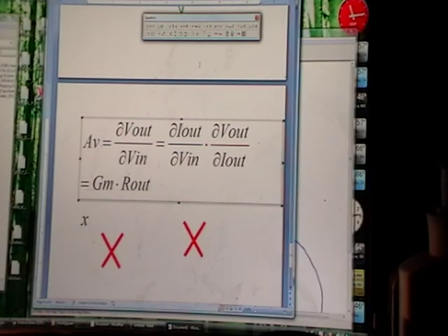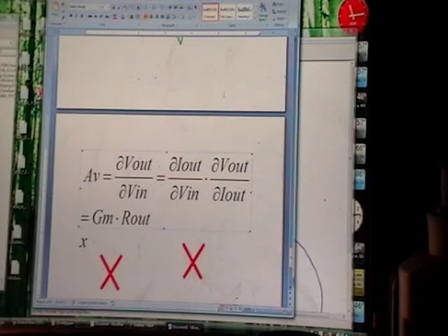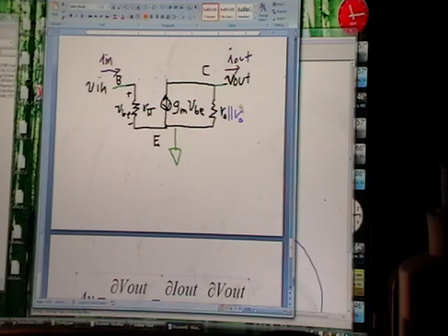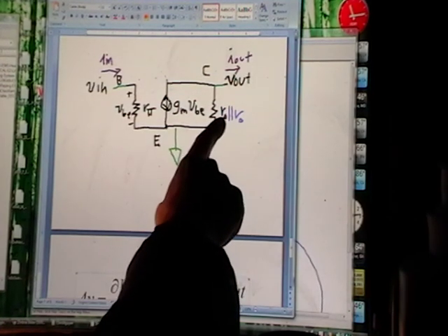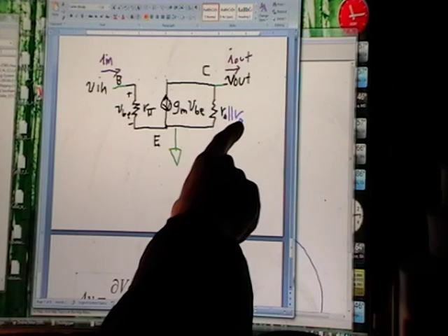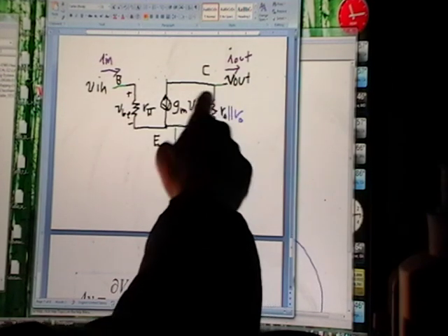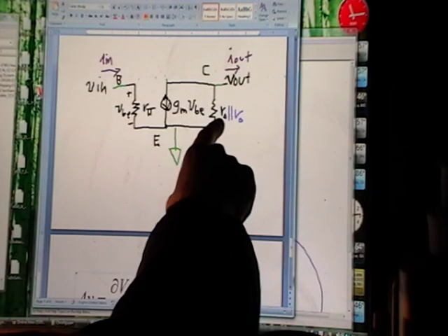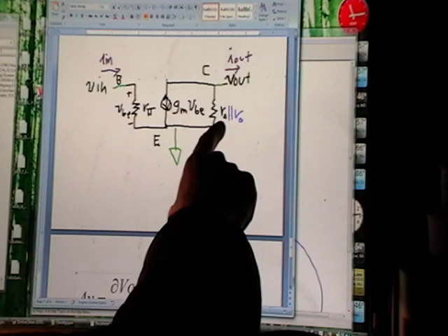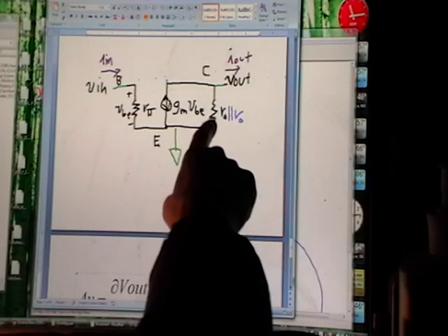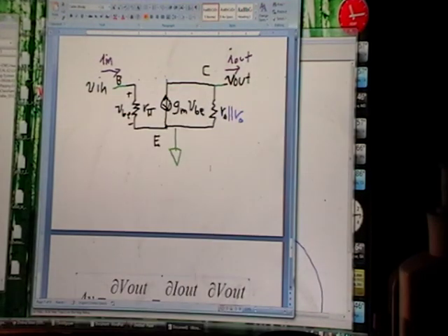I out actually cancels out in these things, but R out is one of the things that can give you a bigger gain. And what you did by using an active load now is, before it was your R in parallel with R out. It doesn't matter if R out is a mega ohm, if it's in parallel with 1K, it's going to act like a 1K resistor. The 1 mega ohm isn't going to have much effect. But if you have 1 mega ohm in parallel with 1 mega ohm, now you have 500 k ohms right here.